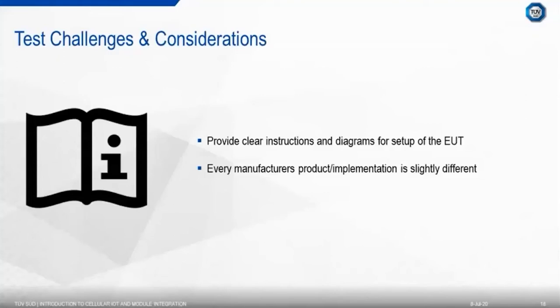It's also essential to consider the normal operation of your product, and this might not be testable in a lab environment. For example, a module that transmits once a day for a few seconds will not be testable. In the case of cellular modules, this is not as important, as the test set can help overcome these issues by forcing the device into a more regular transmit pattern.